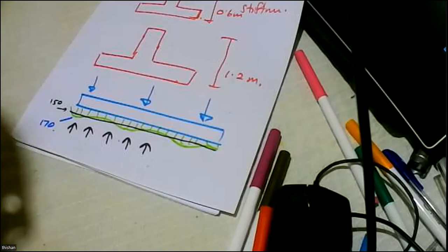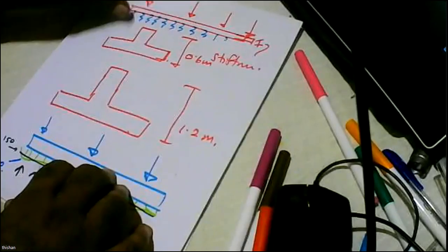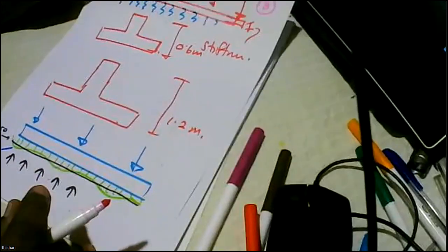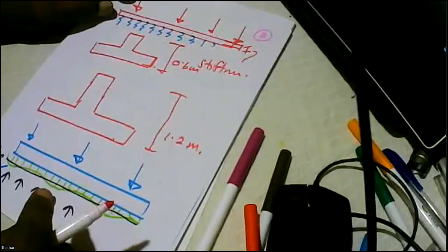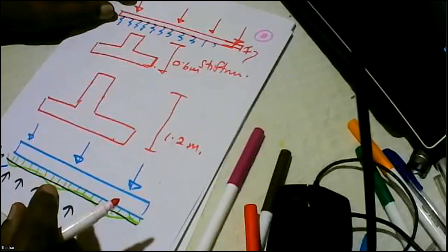But with these Winkler springs, we are providing you with a tool to do experiments in a very short time, because it will not take a lot of time. Once you make the model, you can change the shape of the beam. The depth of the beam can be easily changed within 1 or 2 minutes.